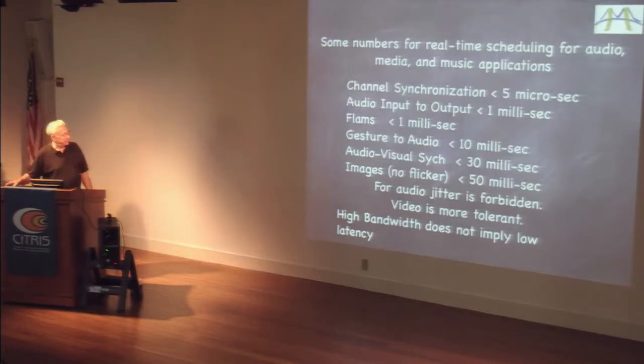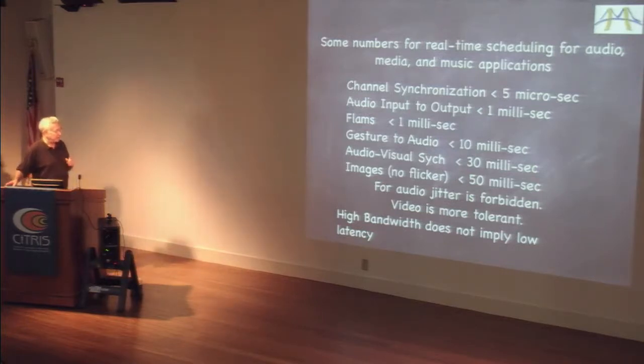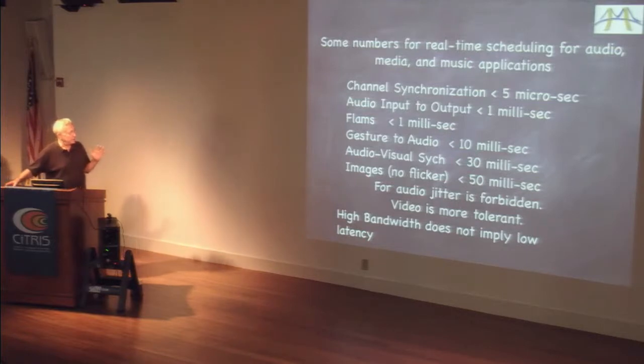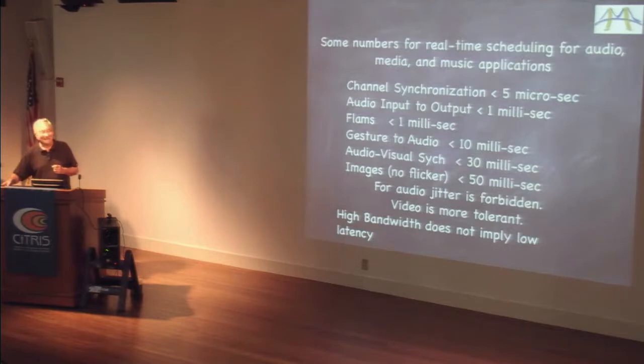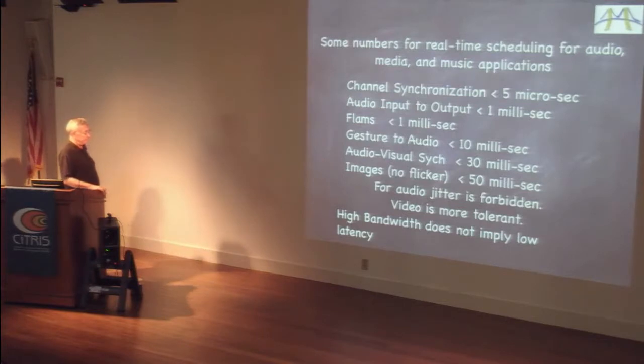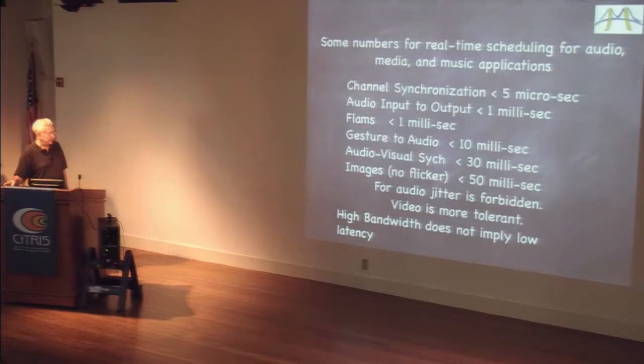And I won't spend much time on the rest of this, but one thing I want to emphasize that's very important is that audio jitter is extremely degrading. Put it that way. It really does have a bad influence, and in fact, the signal-to-noise ratio really can go down if there's some irregularity in the clock or the timing of the samples as they come out. Video is much, much more tolerant.